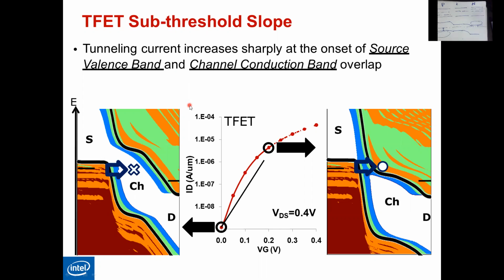the concept of modeling in order to understand, and herein you can also understand the threshold effect and what's called the sub-threshold effect. Because as you can see here, whenever we are below threshold, theoretically in the MOSFET we say that no current will flow. But practically this is not true. In the MOSFET and even in the tunneling field effect transistor, we have what's called the sub-threshold effect. And the sub-threshold effect can be described here by monitoring the current and voltage variation below the threshold voltage.